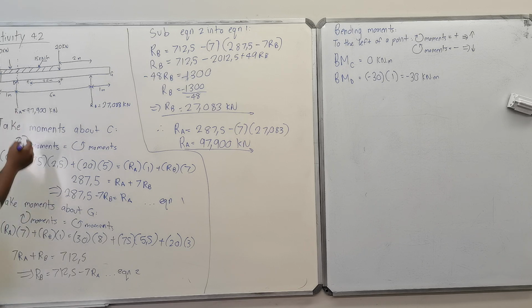So what you would have had to do was work out what the force is being applied at 1 meter. So you convert the small portion into a concentrated load, like how we would do for this entire portion. And how you would do that, you would say 15 times 1 meter, which would be 15 kilonewtons. Yes? And how far away is that from point D? 0.5 meters. Do we understand that? Is anybody confused about what I just did?